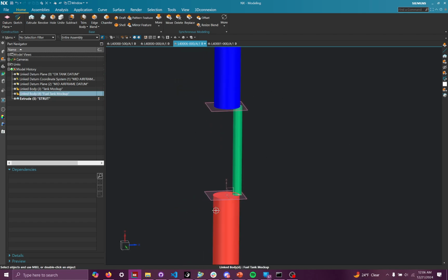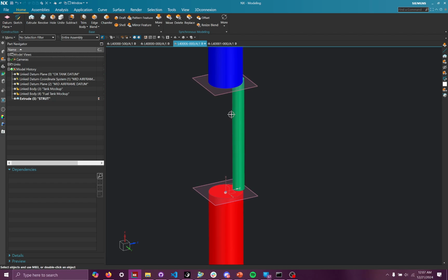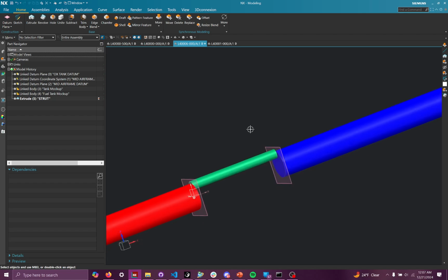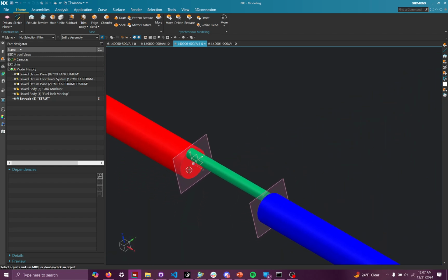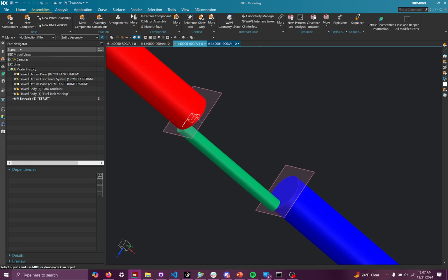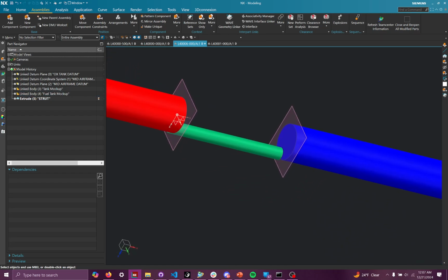So that's the basic mindset, I guess, that you want to have, is only wave geometry link in stuff that you'll actually need to model off of, and otherwise keep it simple and ignore stuff that you won't be touching. So if you ever feel like you need to bring in more stuff, that process of wave geometry linking, well, first off, before you wave geometry link, you have to actually bring in that assembly file that holds the geometry you need to wave geometry link.